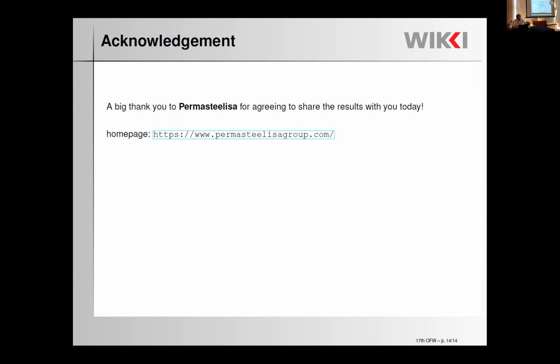Okay, so there are two parts when it comes to that. I made the mesh using the commercial software Pointwise, and some of the interfaces are conformal, some are not. It depended. At the beginning, I was doing everything conformal, but as the client was expecting more and more interfaces, I wanted to make something quicker.